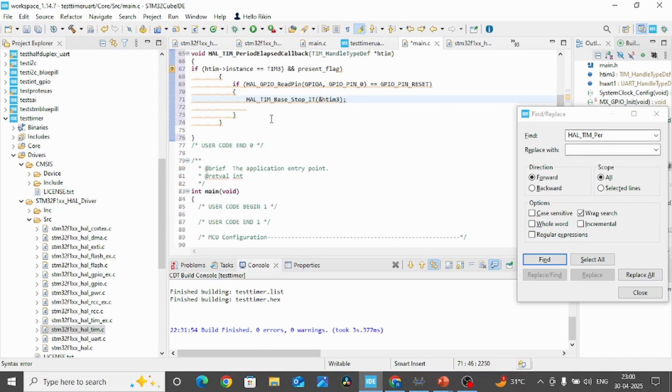Because we have to make sure that the switch stays in the pressed condition continuously for 3 seconds or 5 seconds. So if after 1 second the person releases the switch, the previous interrupt will definitely have been generated, but now after generating the interrupt the user releases the switch, so it will simply come over here and stop the counter from this only, right?